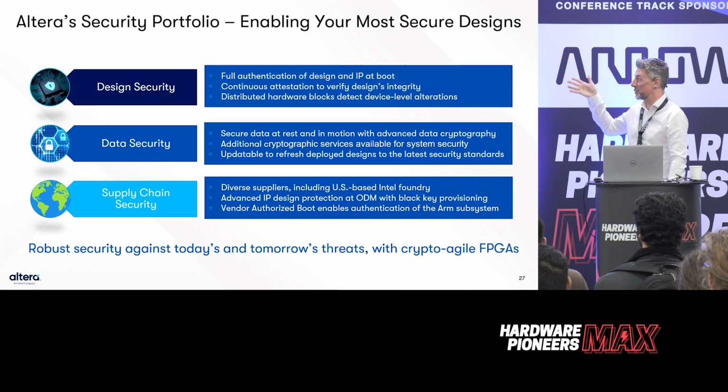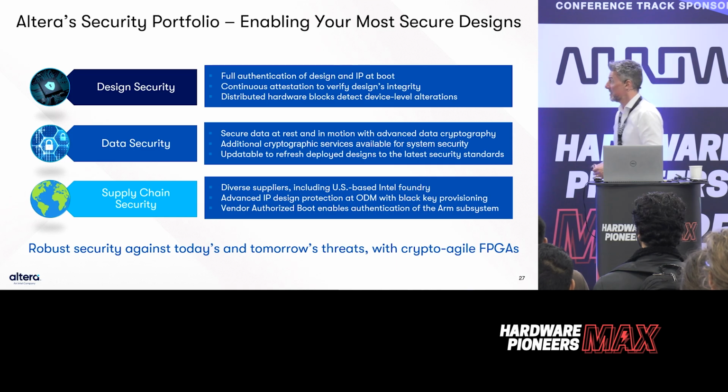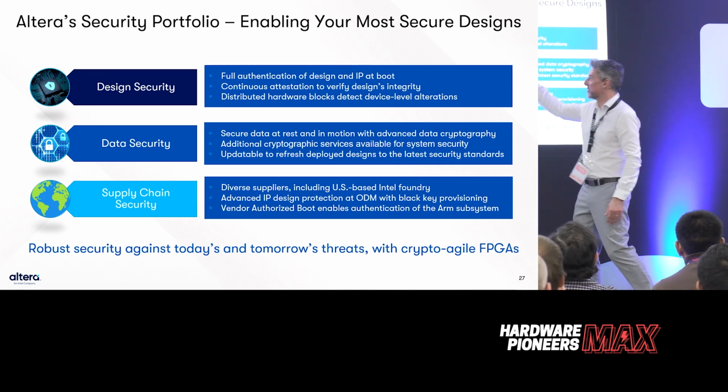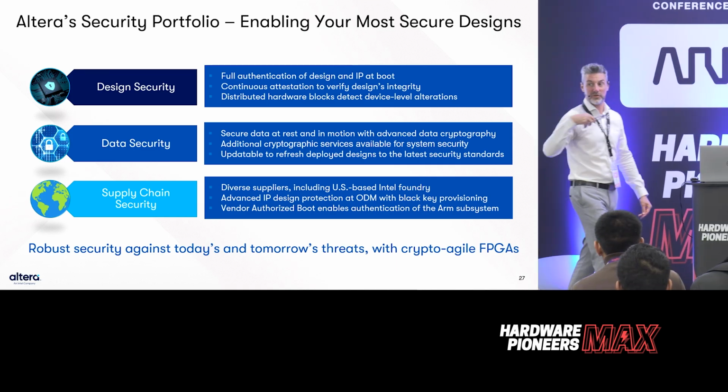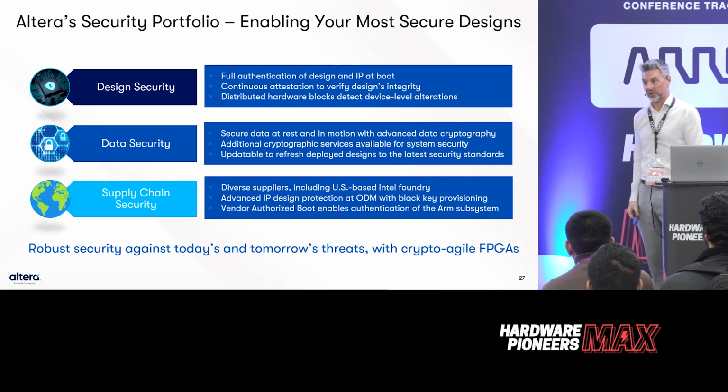Most of us will have some kind of security built into the device for securing the bit stream, thinking about authentication, encryption, and then through to high-level features like attestation, where you can get the FPGA to report cryptographically, securely, what it's actually running on the device.